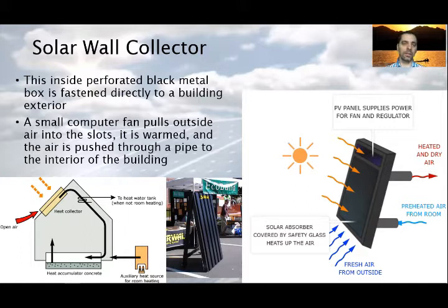Storage can also be handled with rock bins. A blower circulates the warm air from the collector to a bin of rocks, which will absorb most of the heat. When the home requires heat, it is pulled from the rock bin.